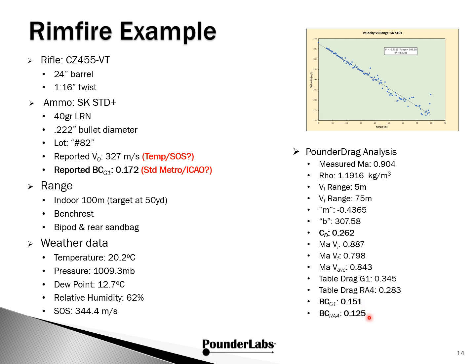You'll notice that this doesn't match up real well with what we see as the reported value. This is fairly typical because we've done a lot of detailed measurement here, and again, we're not even sure what the environmental factors were going in. But for us, the coefficient of drag is really the cornerstone measurement here, and this value actually correlates very well with data from work done by the Ballistics Research Lab in the early 90s. So it speaks to the power of fully qualifying your measurement and recording what you're doing, and you can get much higher quality data, which is really what we're after here.